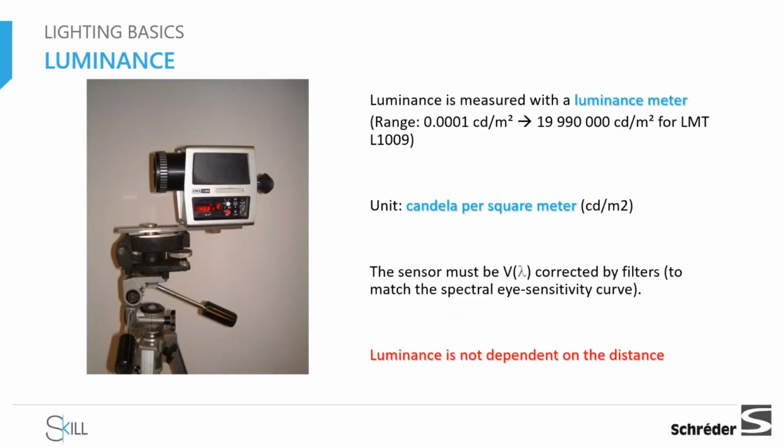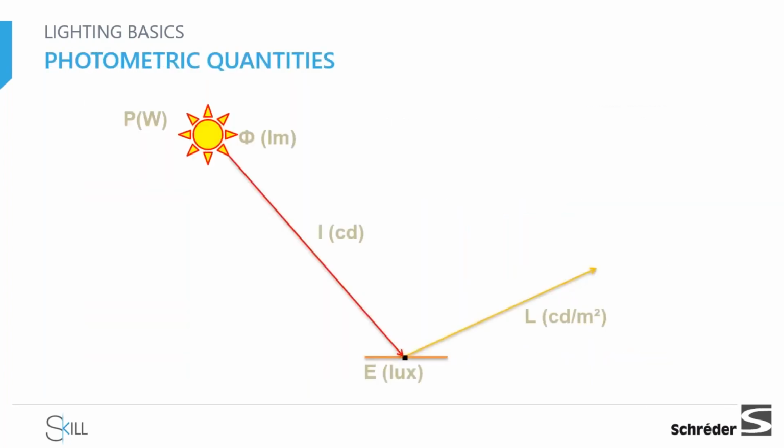To measure the candela per meter square, we will have a device called a luminance meter, and of course, in CIE 140 and 115, we will explain exactly how to identify the location where it has to be kept to do the measurement of candela per meter square. Okay, I think that's all.